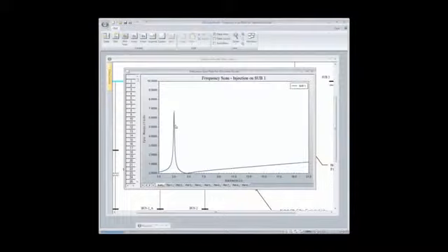Basically, every time you have a combination of inductance and capacitance in any form, whether it's just because of a capacitor bank on the bus or because you have a filter on the bus, it's like one of those balloons, you know, that the clown ties up. Okay, so you're holding that tubular balloon. If you pinch it, it's going to make the rest of the balloon expand. That's exactly what we're doing with a harmonic filter.